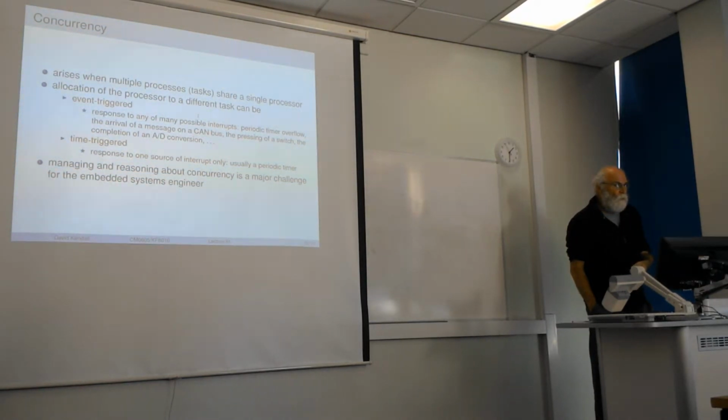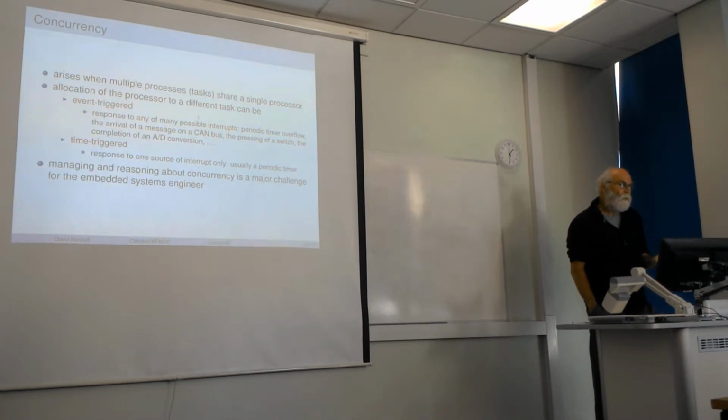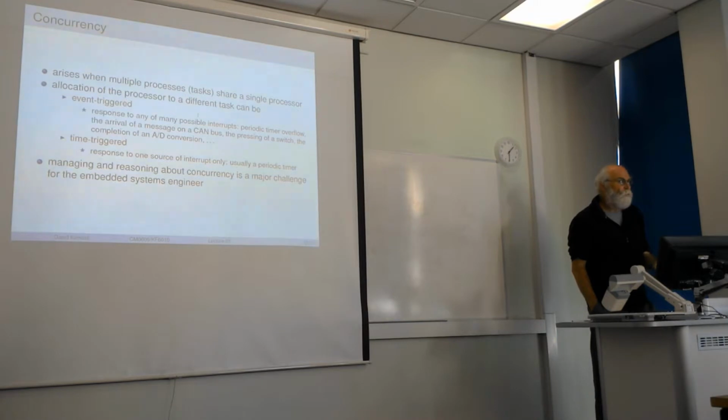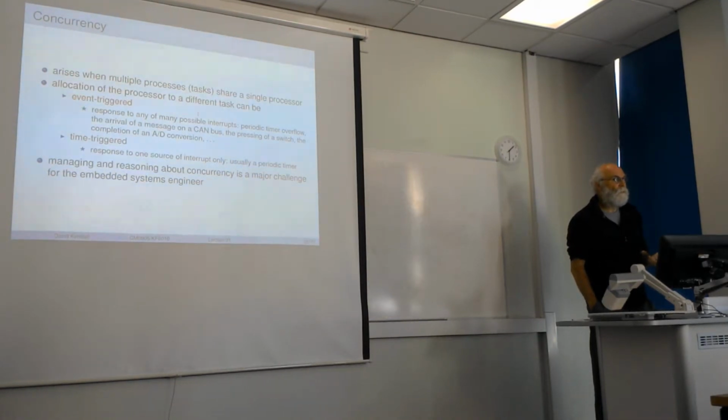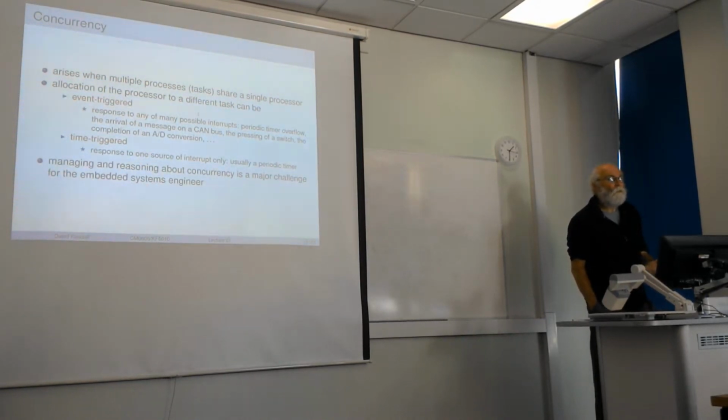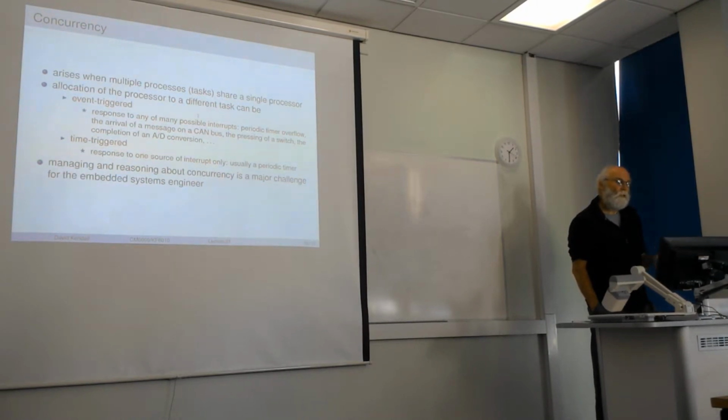Now, you can make an argument for both of these approaches to building your system. In the event-triggered case, it might be that you can be more responsive, at least for some of your crucial interrupts, but it may be much harder to reason about the behavior of your system in all possible circumstances.